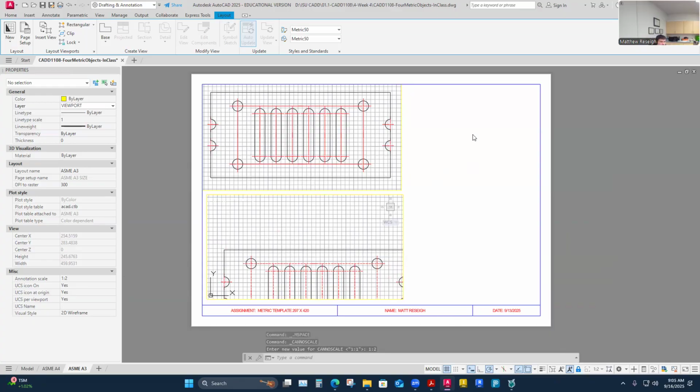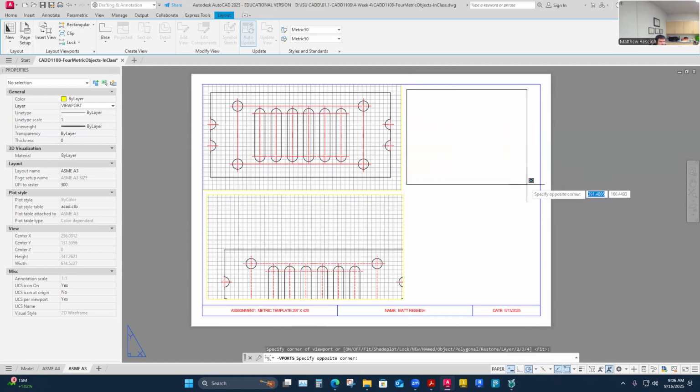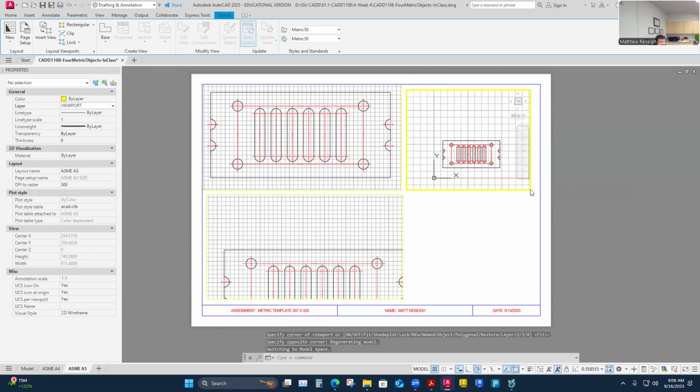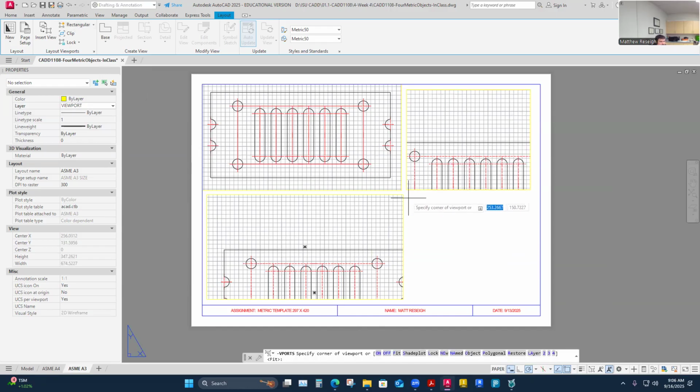I'm going to add two more viewports here too. They're all going to show that little one, but I'll move the view. This one I won't want to look at that, so I'll move where it's looking when I draw another shape. For the other rectangle, I think I put the smaller little gasket looking part up here in this corner. I'll also zoom it to a 1:2 and lock it down momentarily. And then I'm going to put one more down here.